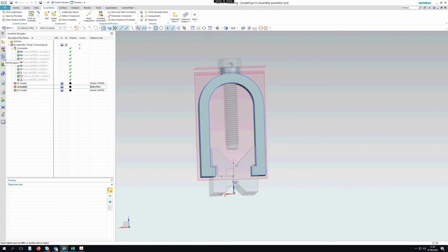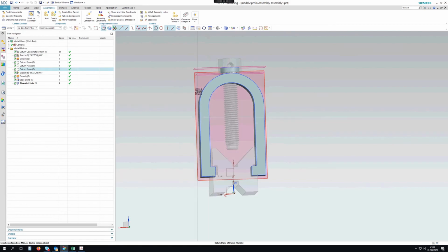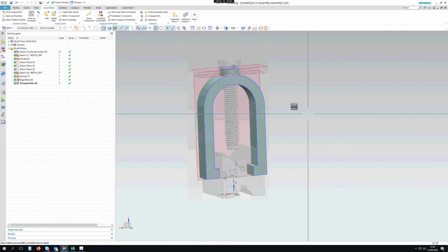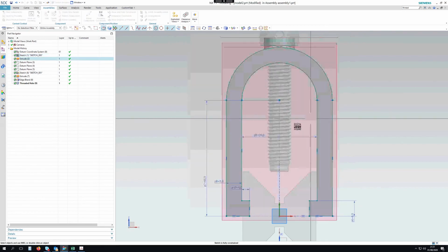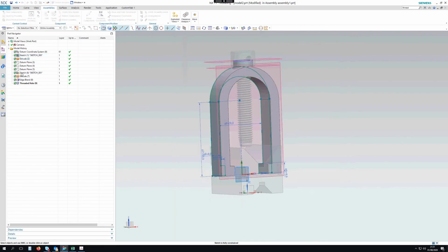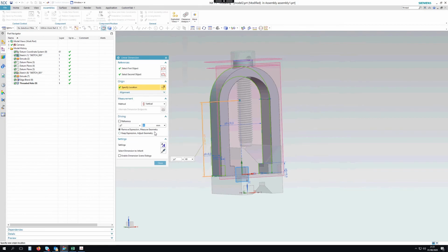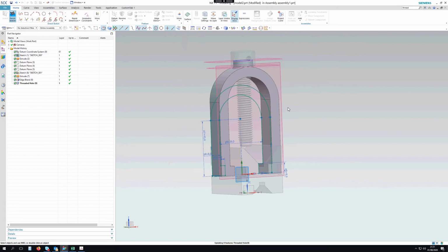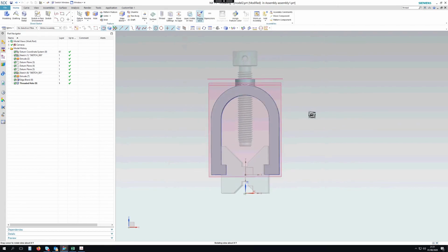Now if I go back to the part navigator, I can see how this item was created. And now I can modify it relative to the assembly and see what's going on. And this is where you may want to double click the sketch, because it will modify it with everything else active below. So this dimension that I used originally here, this will be a little bit big. Let's go for 50, maybe 45. Let's see how it updates. Let's go back to home page, finish. So if you look there, that's more like what I wanted.